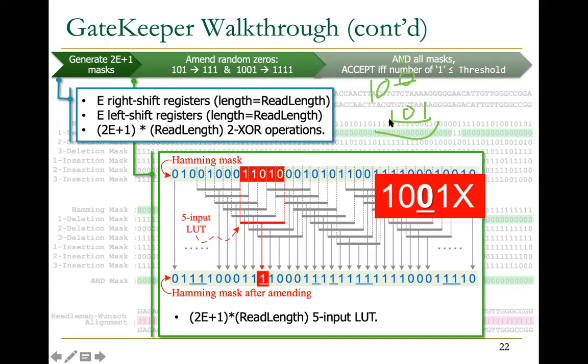So now, in order to be sure that this is a 1, you really need to consider the 3 bits together. Now, when we have 2 zeros, why not just consider this case, 1, 0, 0, 1, which is 4 inputs rather than 5 inputs? The problem is that sometimes you don't really get the exact pattern 1, 0, 0, 1. What you will get is something else, maybe something, then 1, 0, 0, and then that is the end of the 4. So let me write it.